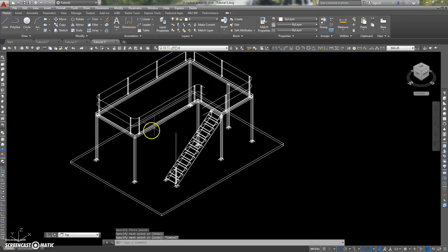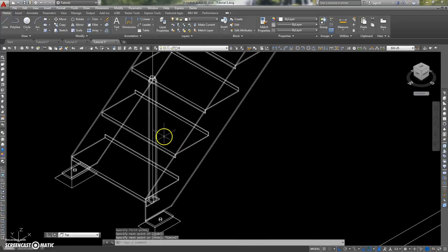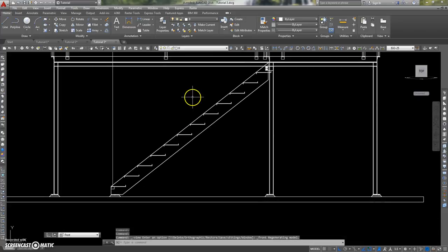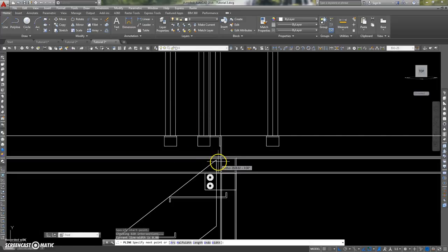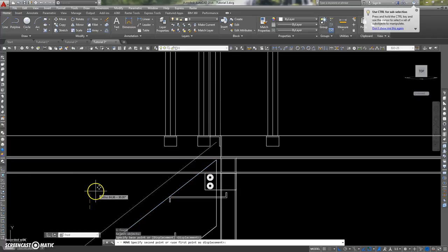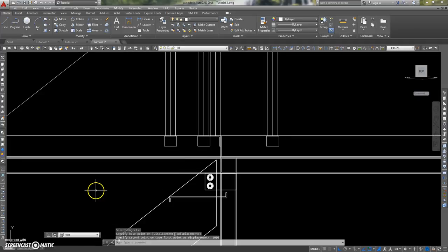We're just putting a line up here temporarily. We'll explode that stair, that piece of block. So remove that piece out of it. We're still left with the angle at the bottom. And we want a polyline to run along here up to there. Now you can move L for last. Hit enter, and you're going up 1,000 millimeters. Your standards may differ from this.